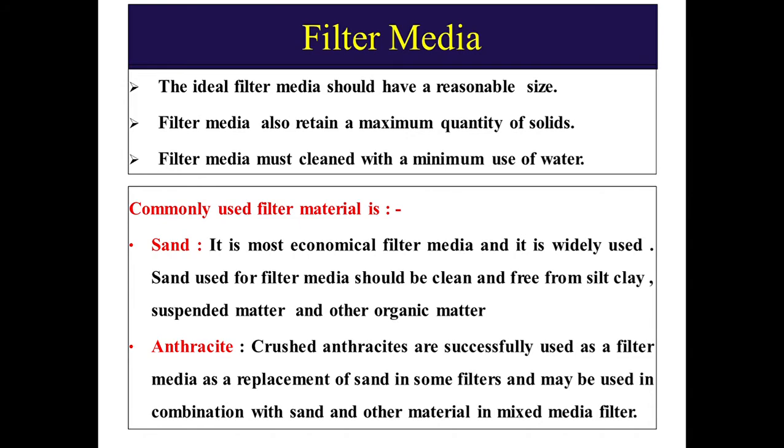Then, filter media. The filter media is a very important parameter for the filtration. The ideal filter media should have reasonable size. Filter media should also retain a maximum quantity of solids. Filter media must be cleaned with the minimum use of water.